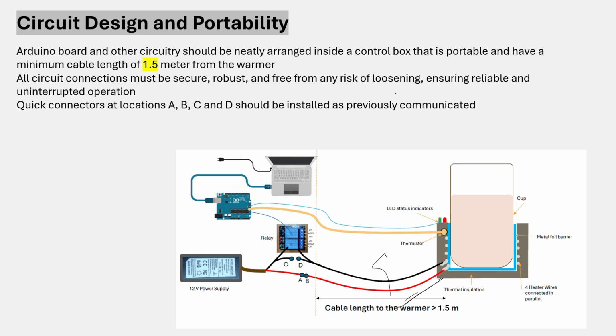For portability, what we wanted was how you can neatly arrange all these components inside a control box. And by components, I mean the Arduino, the power supply, the relay, all that, such that they are neatly arranged. And when you move it for test and everything, it shouldn't be that there's a loose connection and it's not working, there's a short circuit, things like that shouldn't happen. Okay, so what is your plan to secure? What is the plan to connect? Are you soldering the joints? What kind of connectors are you using? Those are the things that we are looking for.